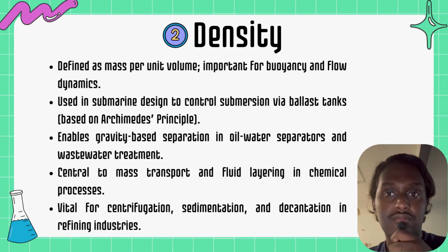Second, density. Density is defined as mass per unit volume, which is important for buoyancy and flow dynamics. It is used in submarine design to control submersion via ballast tanks, based on Archimedes' principle. It enables gravity-based separation in oil-water separators and also wastewater treatment.